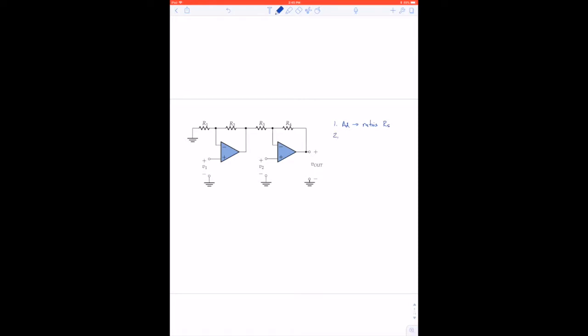We'd also like to find the common mode gain, so we can write an expression for the common mode rejection ratio, right? So let's find the difference gain expression first, which will allow us to see what the ratios of the resistors need to be for it to be a difference amplifier by using superposition. So to use superposition, we're going to first go ahead and ground V1